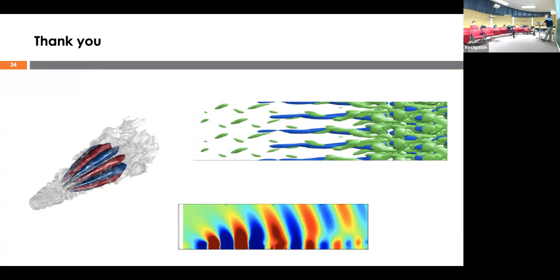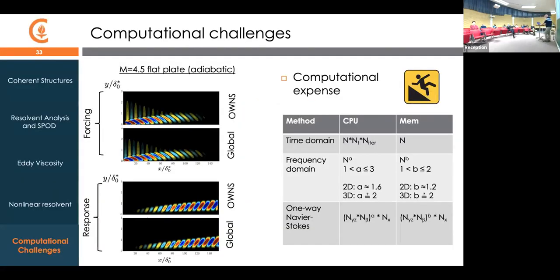Tim, may I ask you a question about the last slide, the one before? Yeah. I really like this comparison, which is remarkably good. But the one thing I spot is the Mach number is 4.5. So I just wonder, do you get the same amount of agreement when you lower the Mach number, for example, to Mach 0.1? Yeah, for a boundary layer you do. We've done this over the entire regime from essentially incompressible all the way up to sonic.